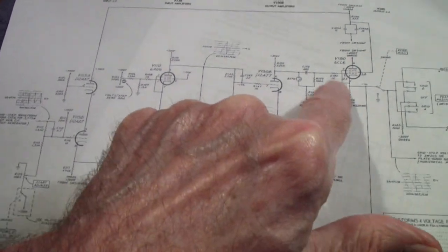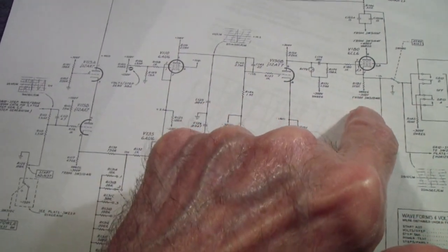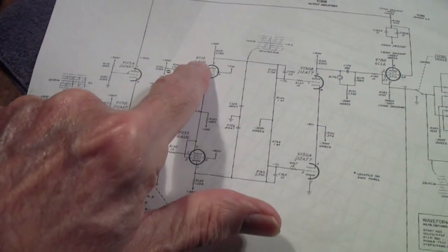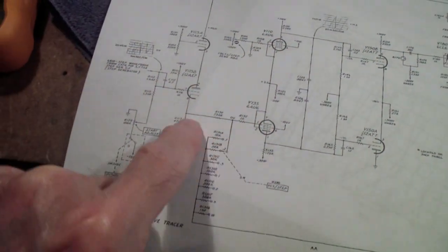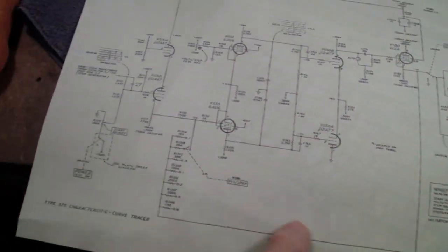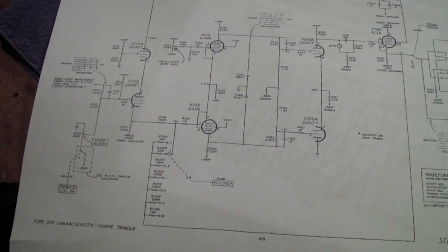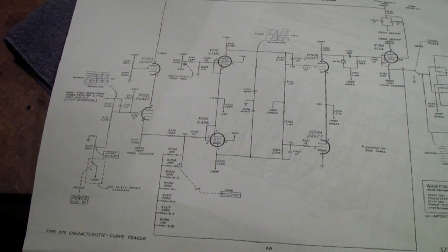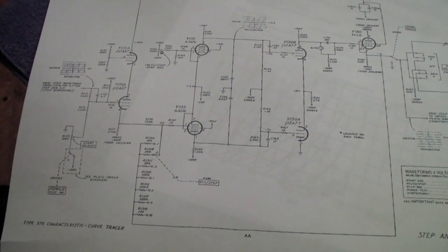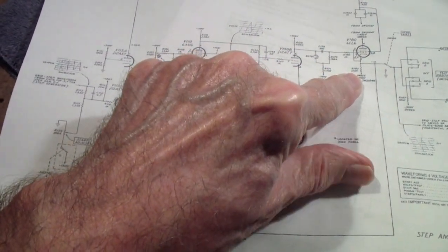And that means that a signal that feeds from here through to this supply and then winds up affecting one of these other supplies doesn't get reinforced by this feedback loop. If you've looked at some of my videos on control loops and control theory, you'll understand a little better what we're talking about there. But anyway, that's one of the little changes I had to make to get this scope working again.